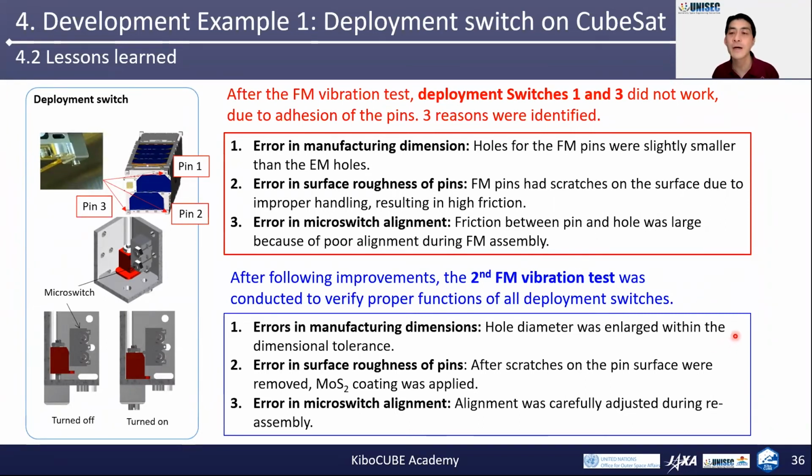Regarding the first error, the hole diameter was enlarged within dimensional tolerance. Second, after scratches on the pin surface were removed, MoS2 coating was applied. And finally, alignment was carefully adjusted during the reassembly of the flight model. These pins worked well in the actual flight.